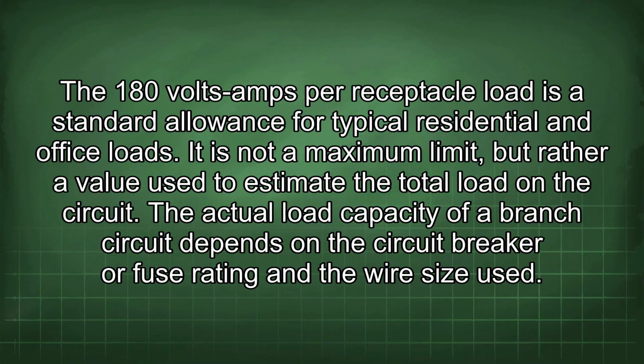180 volt-amps per receptacle load is a standard allowance for typical residential and office loads. It is not a maximum limit, but rather a value used to estimate the total load on the circuit. The actual load capacity of a branch circuit depends on the circuit breaker or fuse rating and the wire size